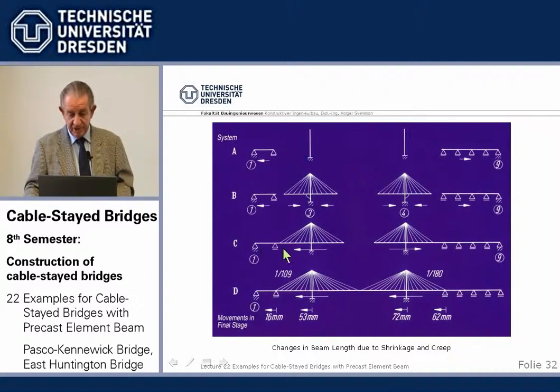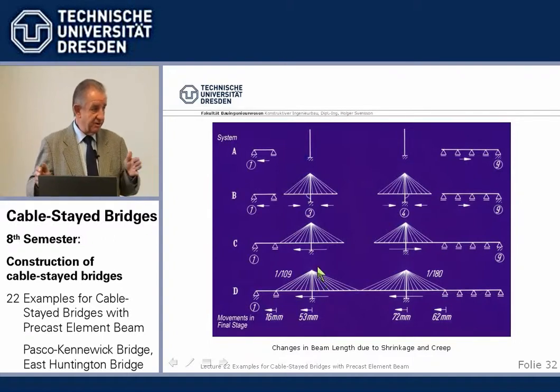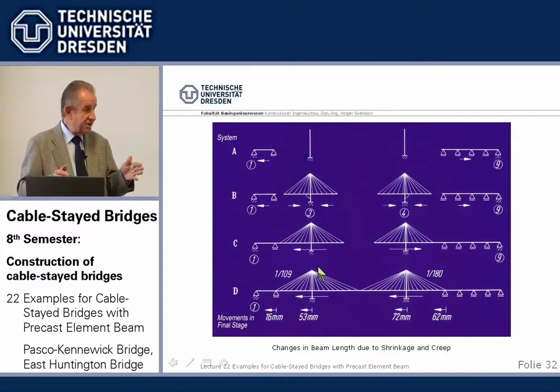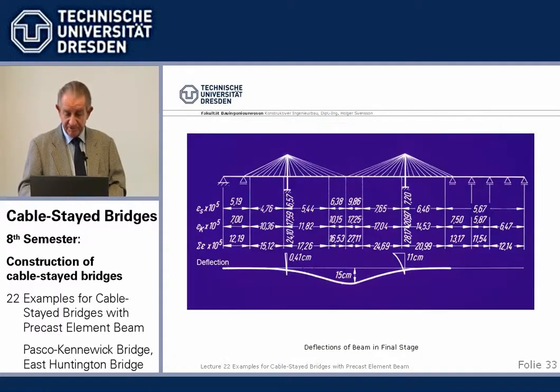Then we close the side spans. We have a permanent fixed point here, it moves there. We have a temporary fixed point here, it moves there, and goes on. And all this has to be carefully added up so that you end up with exactly the bridge you want, taking into account the various movements due to change of fixed anchorage, typical for all bridges.